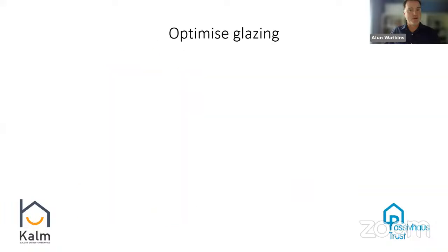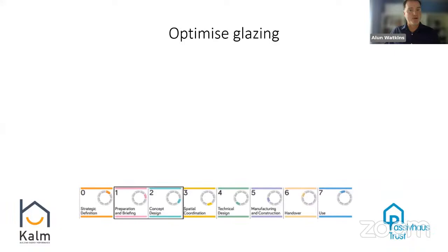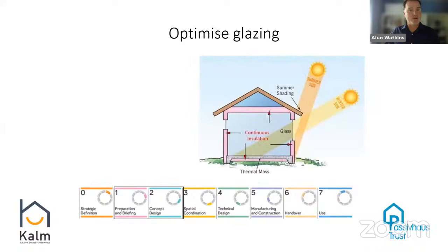And the other significant factor here is glazing, same sort of time. And again, looking at orientation and glazing proportions, they're pretty inextricably linked, because it's the windows where we get both the heat gains from solar gain and heat losses through the transfer of heat. So what we can see here is the difference between the winter sun and summer sun. Winter sun is much lower in the sky, and that's when we want to get the solar gains, whereas the summer sun is much higher. You can see there the overhang of the roof is actually stopping the sunlight directly hitting the glass.